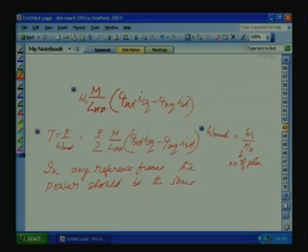Now for a 3-phase power, power based on single phase equivalent quantity is equal to 3 into V phase into I phase for a balanced system. Suppose we are sending that same voltage waveform to a resistive load to make it simple. This transformation, the voltage and current transformation, is not independent of the load. So let us take a resistive load. So 3 into V phase into I phase, 3 times for 3-phase power.